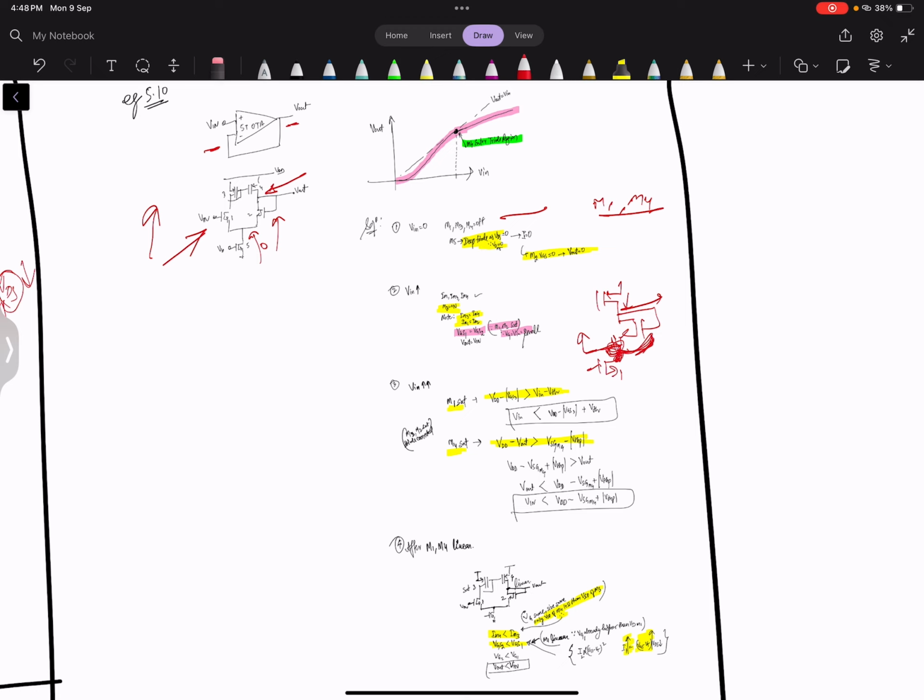And an important point is, since Vin is small, we can say that M1 and M2 are in the saturation region. Now if we increase Vin, what will happen? Where is the danger? The danger is, if the input voltage is increased, M1 and M4 will go into the linear region. Why is that so? Because M3 and M2 are diode connected, so there is no issue for them. M1 and M4 will go into the linear region, and the VD of M1 should be greater than Vin minus VTH, and VD is VDD minus VGS of M3. So from there you get this equation.